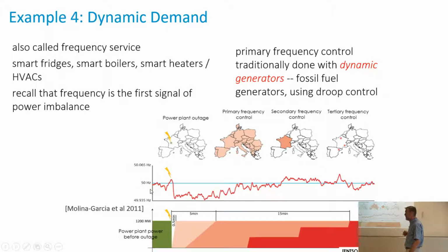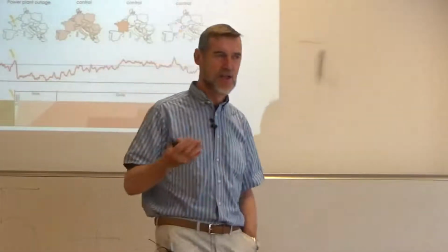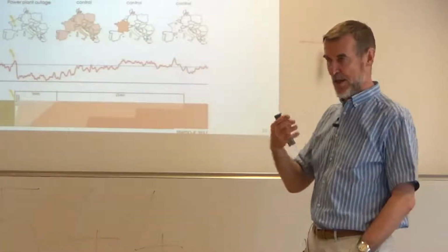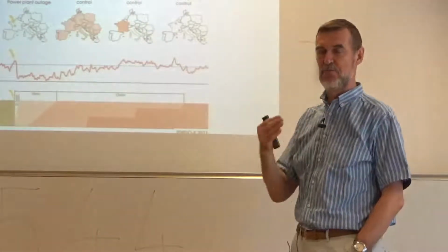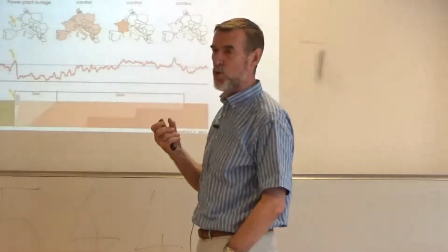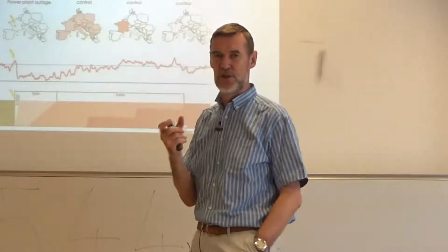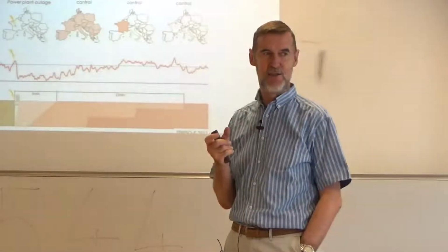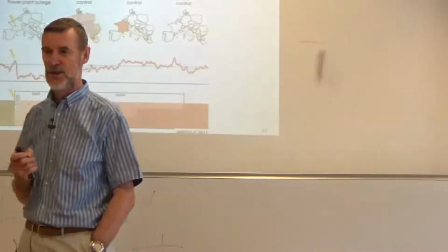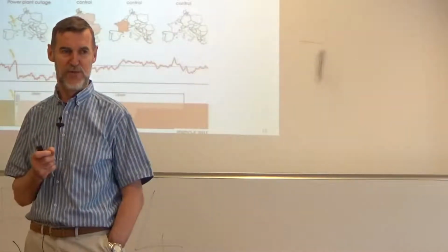So originally, because AC grids have been made by big rotating masses that are the generators, when there is a power imbalance, it's immediately visible on the frequency. So the inertia of the generators mitigates the imbalance, so it has a stabilizing effect, but only for a very short amount of time. But that's the first stabilizing effect that AC grids have been living on over decades. This is why AC grid is such a powerful system.